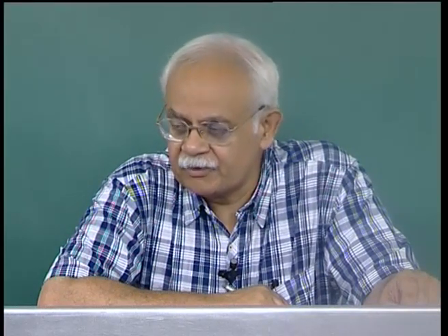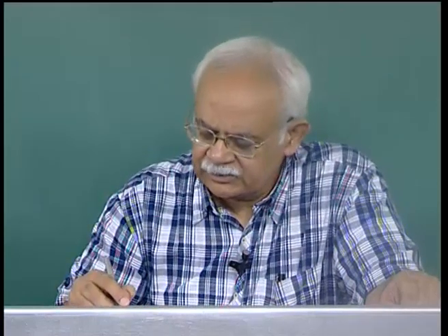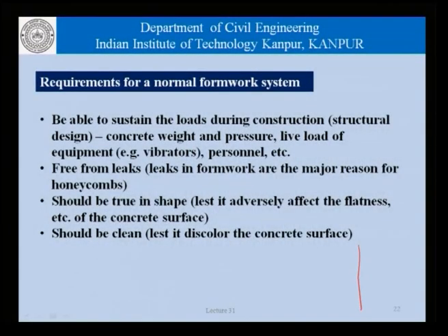Now, this is the general discussion on any kind of formwork. We must also remember that once the concrete is cast against formwork, that is, if we have this as my formwork panel against which some concrete has been cast, and this concrete has reinforcement, then this distance here, the concrete here is really the cover concrete. We must remember that depending on whatever happens at the formwork level or in the formwork, the properties of the concrete in this portion here are the ones that are likely to change most.